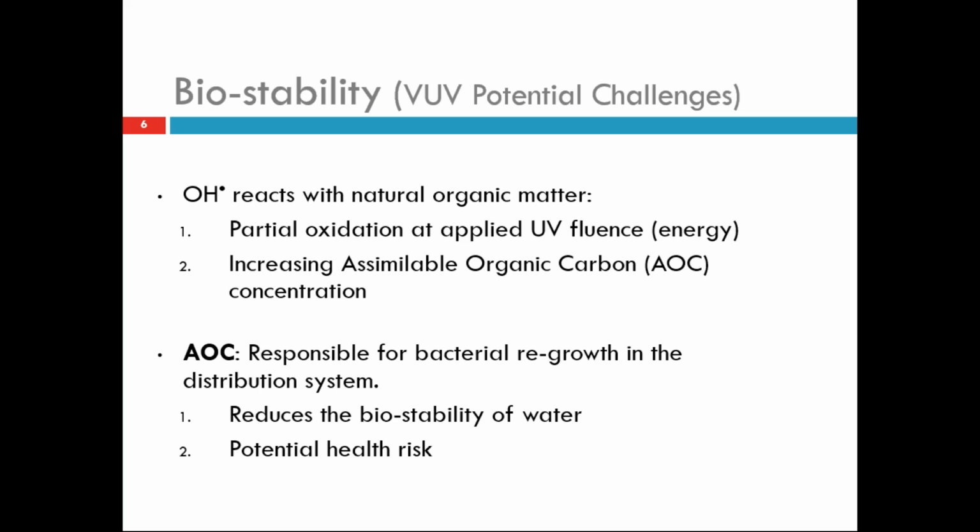Now, AOC is responsible for the bacterial regrowth in the distribution system. The bacteria present in water can use AOC as a food source for rapid growth. Hence, if we have high AOC in our water, that means it's more biodegradable, so it's lower in biostability, thereby a potential health risk.